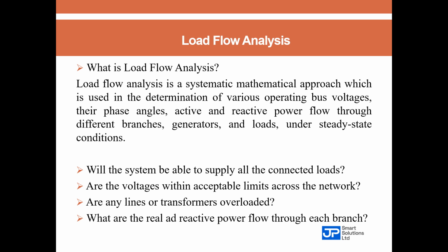Redistribute the loads and plan for an upgrade. However, without load flow analysis, they would have continued guessing or continued assuming that the problem was from the utility. And the problem with this is you are wasting both time and money.